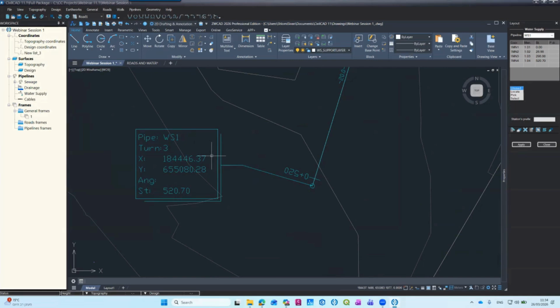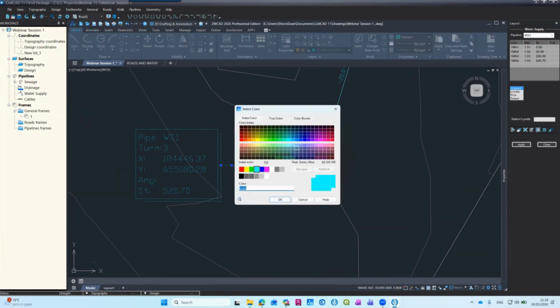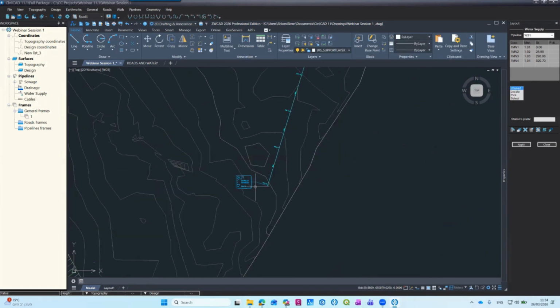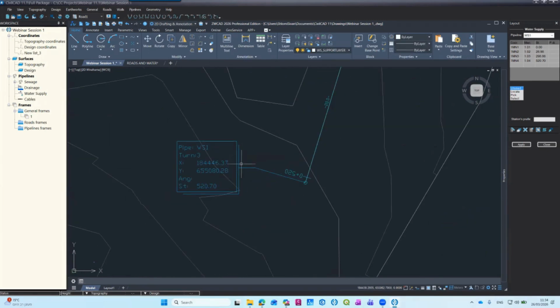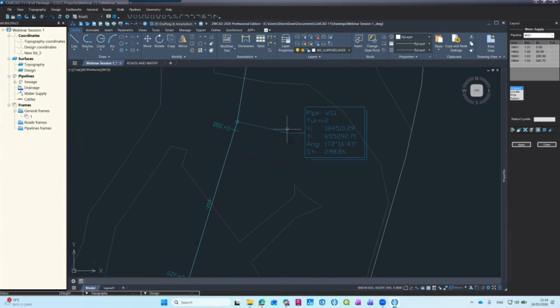Okay? So I can take this, let's give it another color, say like this. And then, nice thing about the M leader is that I can also play with its location. So, for example, I don't want it to be here, I want it to change. So I'm not moving, I'm stretching, right? So it's an M leader with 2 legs.